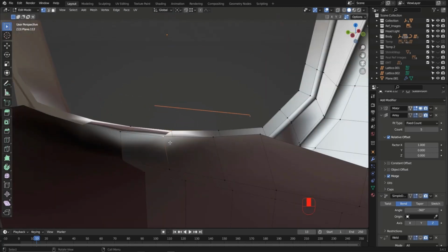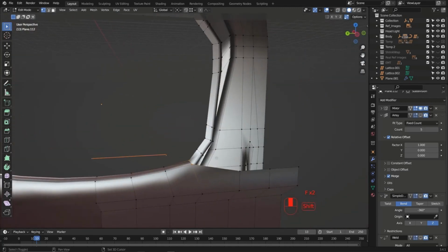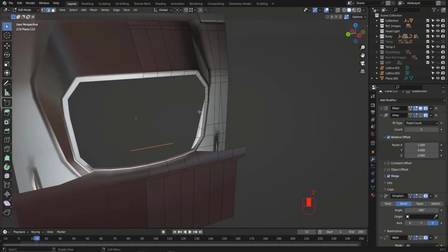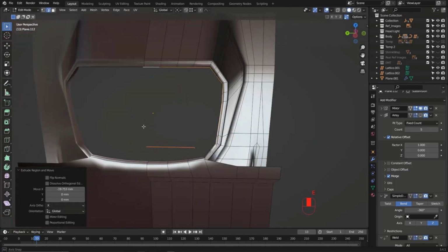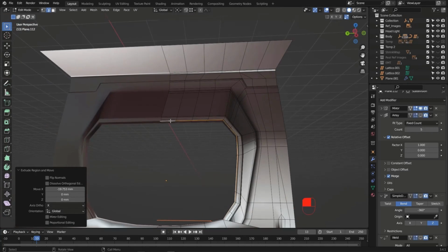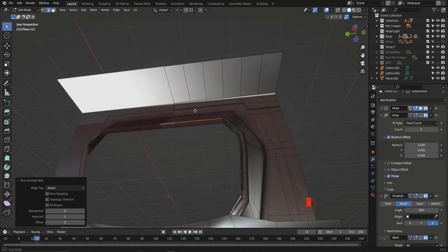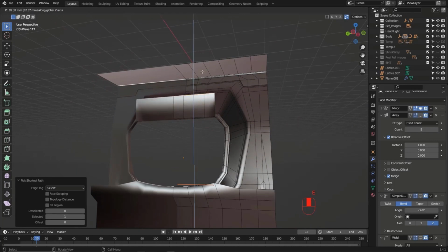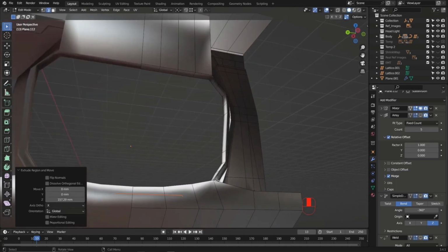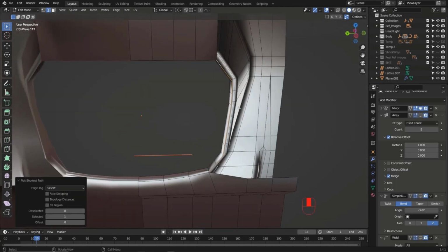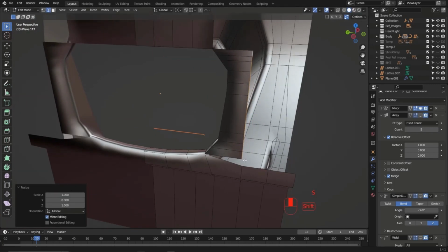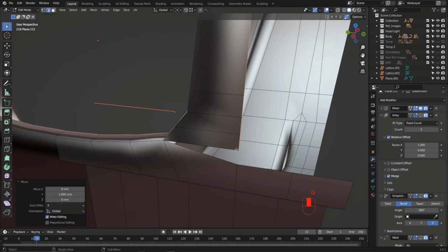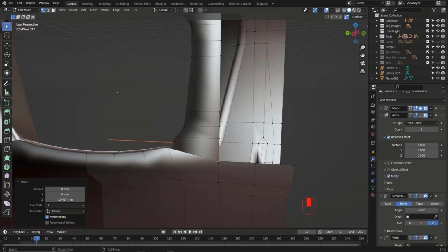And let's create a face here, grab this with this, hit F and F. We can select all of these edges and extrude them, hit E right here maybe. And extrude some of them out. Let's take these up, hit E to the Z, and let's move those over here for now. And these vertices maybe, or edges, we can extrude them like that and flatten these to the Y. And let's snap this line with this one, grab this, hold control and snap it right here to merge it. It should be merged by now.